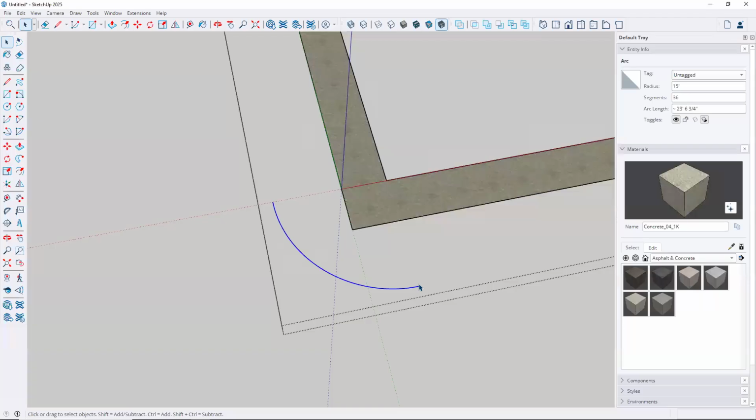Okay, what I'm going to do now is draw lines. L, enter. Actually, L already takes it. I'll start at this endpoint and just draw it straight up. And it's already on the green axis, so I'll take it. But if you're not sure, just keep going all the way up like this. And then you draw another line from here across that way. Let it hit the endpoint. See how that fills up?